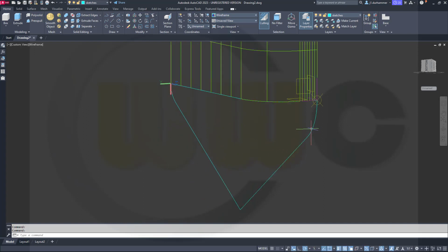Now this should be a polyline here. That's already, no, this one should be a polyline as well. So let's go for p-edit, go for multiple, select this one and that one here, right click, yes, join them, fuzzy 0, enter.